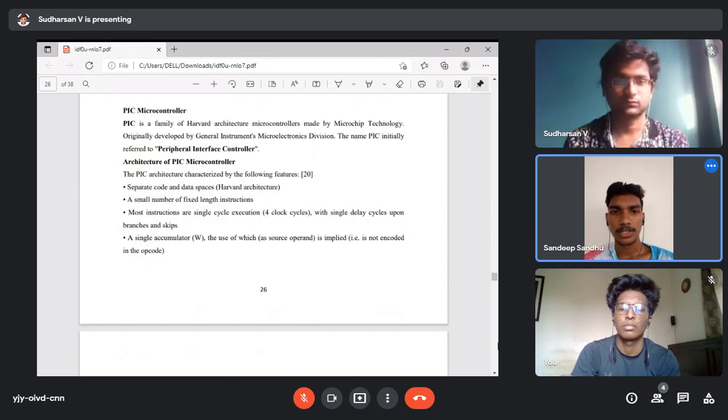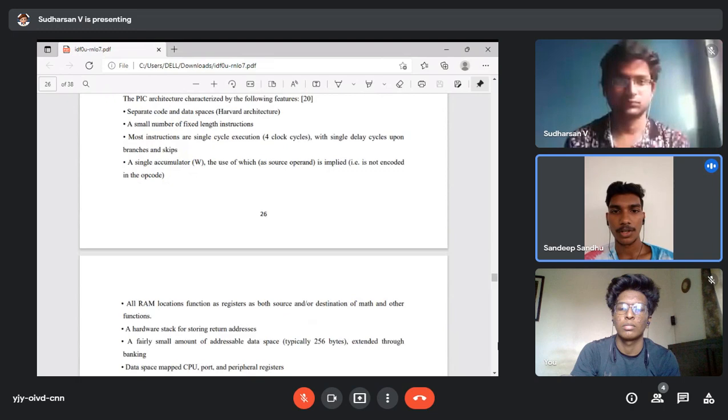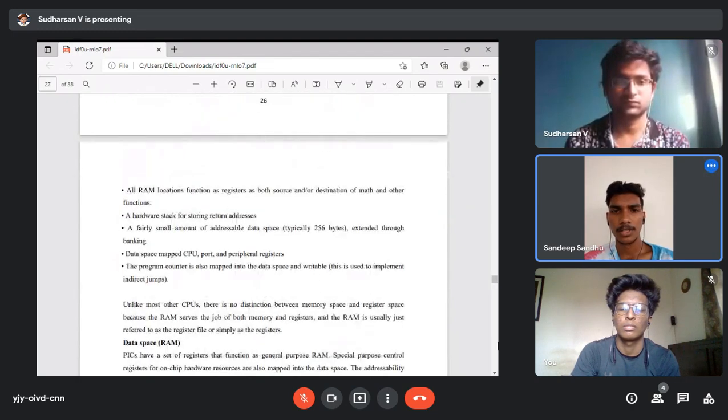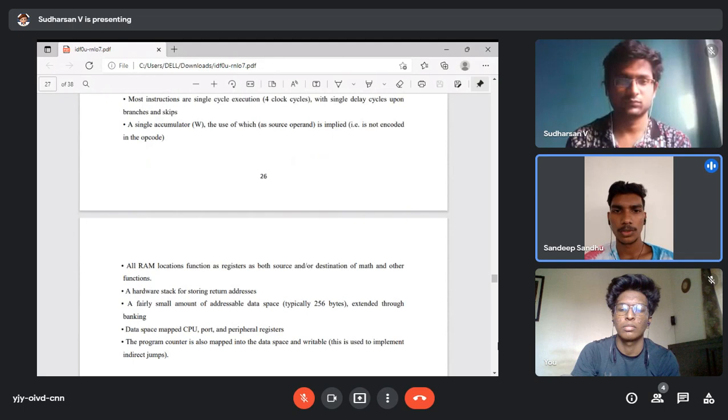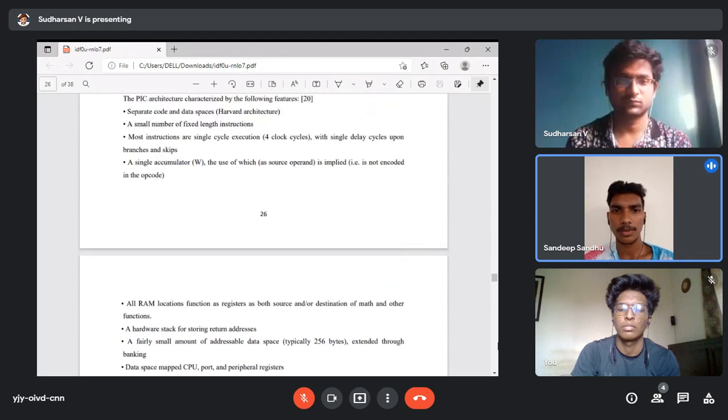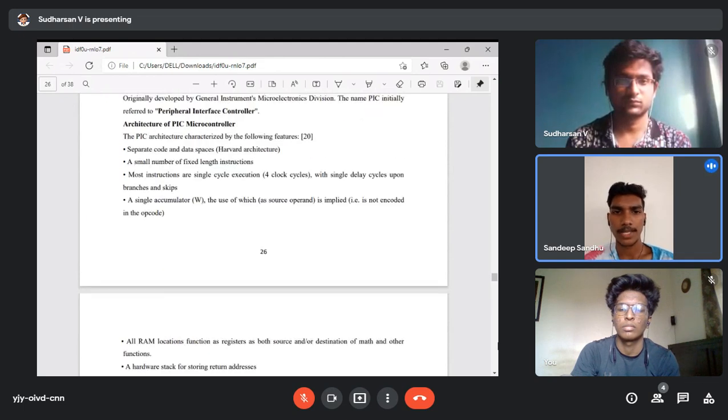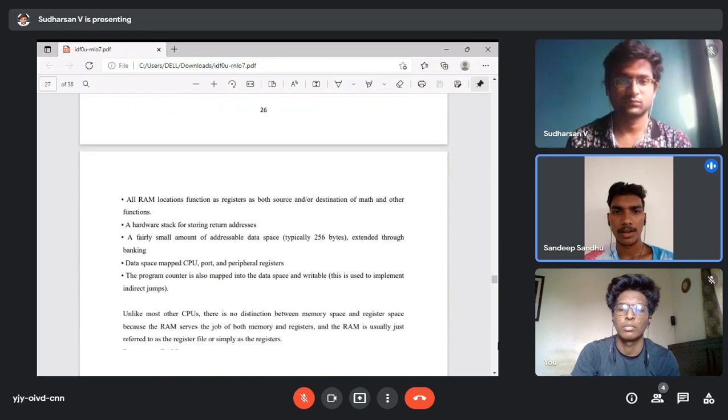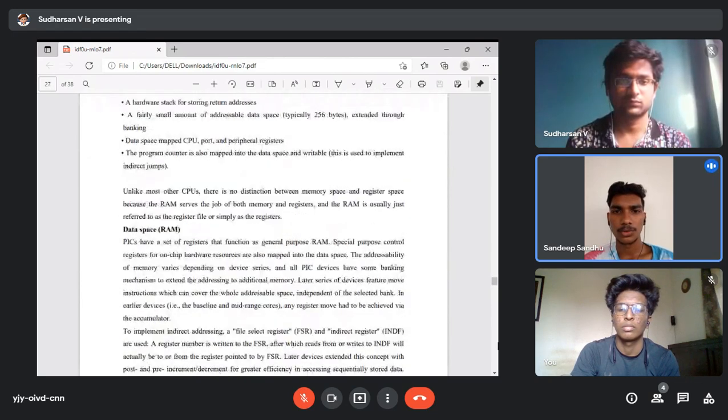The word size of PIC can be a source of confusion. All PIC handle data in 8-bit chunks, so they should be called 8-bit microcontrollers. However, the unit addressability of the code space is not generally the same as the data space. Stacks. PIC have a hardware stack, which is used to save the return address.